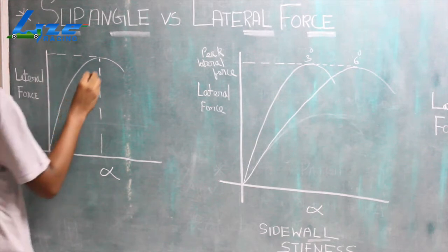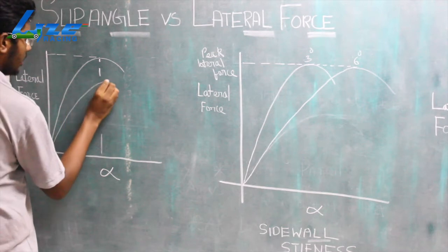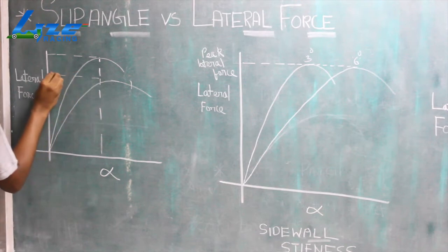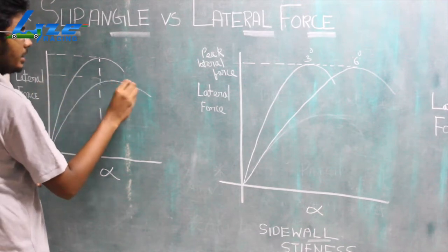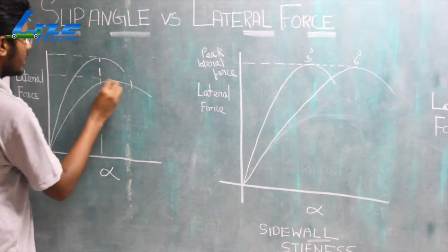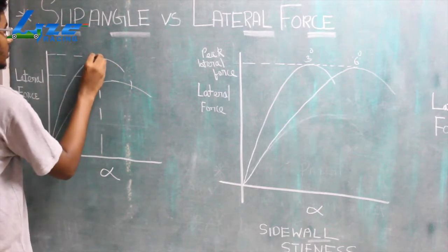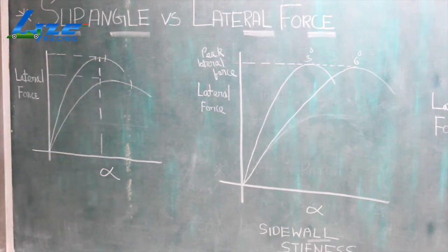Now suppose we increase the range of the slip angle to give us the same peak load over a wider range. This is used for FSAE teams because our drivers aren't well trained. So here we have a larger range of slip angle where we can get a peak load, whereas in the other case the range of slip angles is very small. Small slip angles are used in Formula cars and for well trained Formula 1 drivers.